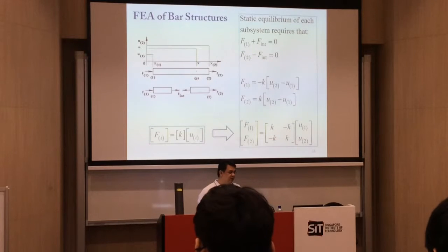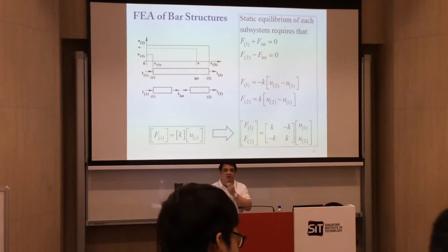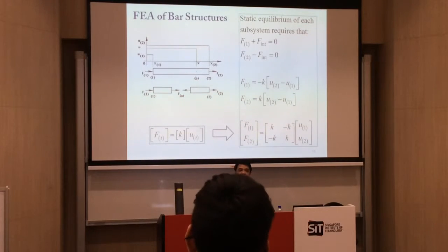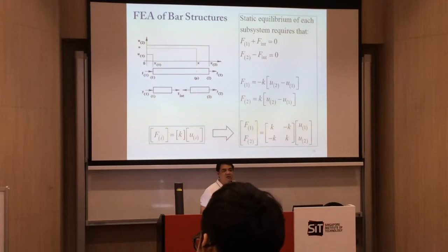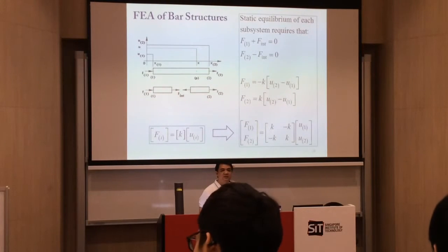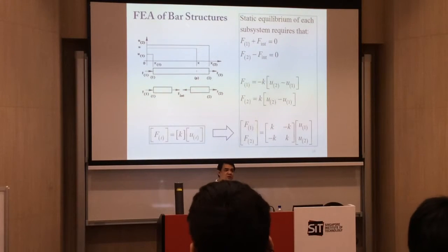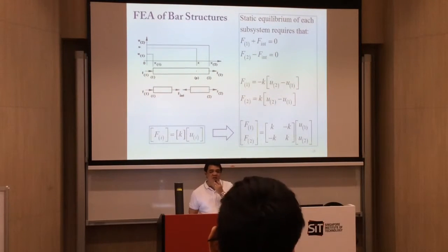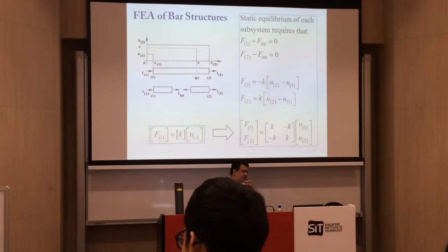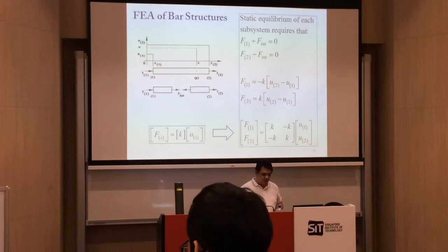the type of element that you're using is a plate or even higher, and then the assumption that you're having is quadratic or higher. Linear, in many cases, they're not allowed to bend. So if in case you want to use linear elements, you need to have more elements, or you have to increase the number of elements to be able to simulate the bending of your structure.